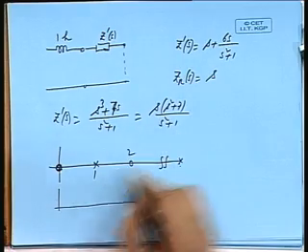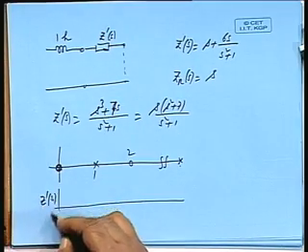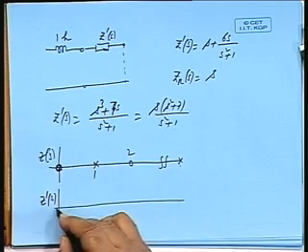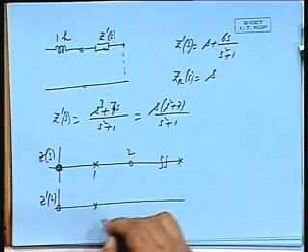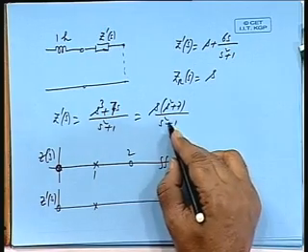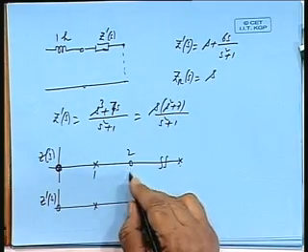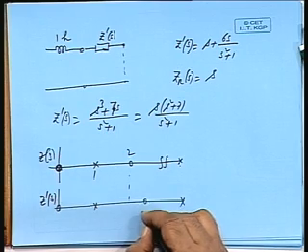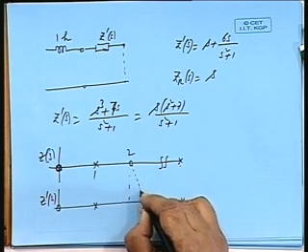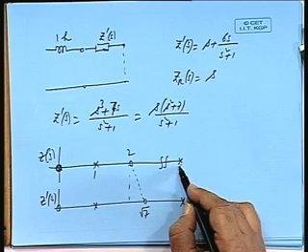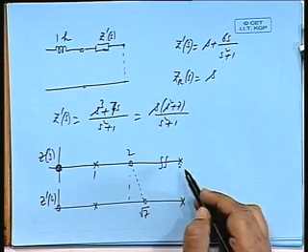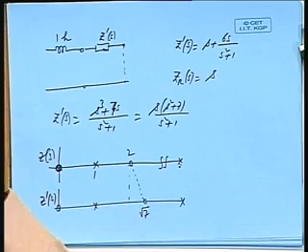So, under the new situation z dash s is having a 0 once again at the same point, pole at the same point, this pole is also at infinity, but here, earlier it was 2, now it is root 7, now it has drifted to this side. So, the 0 here has drifted towards this pole which has been weakened. So, wherever you are weakening the pole, the zeros will drift towards that.